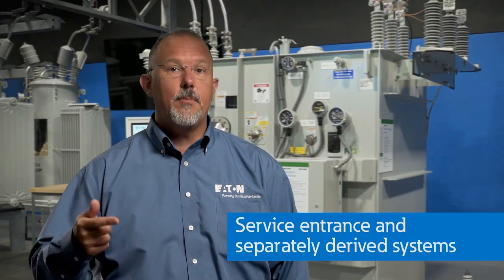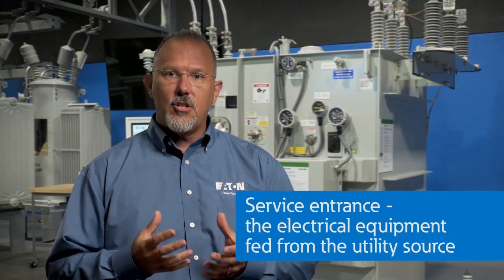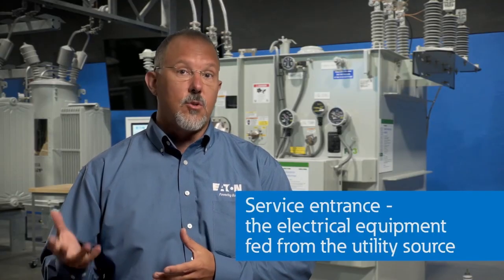For a larger electrical system, we have to consider many other things to properly ground and bond this electrical system. We will give a few examples of components and systems to hopefully clarify any confusion that may arise. Let's talk about two important terms: service entrance and separately derived systems. Simply put, think of service entrance as the electrical equipment fed from the utility source. This may include a transformer, a service disconnect, or other protective devices. There are very specific rules in the National Electrical Code for service entrance equipment and grounding.